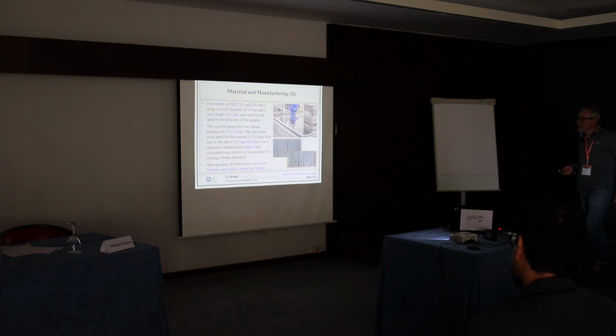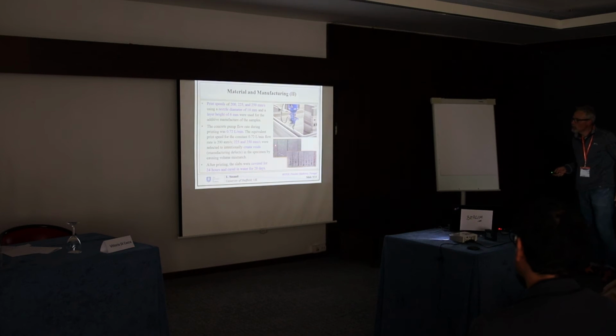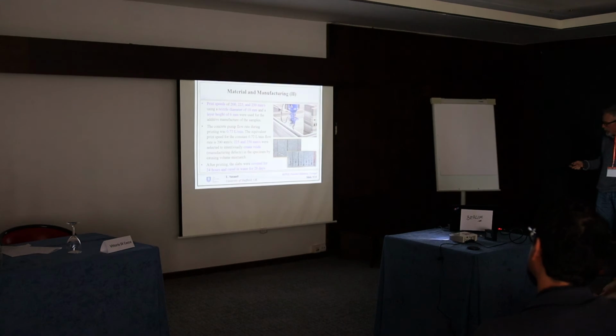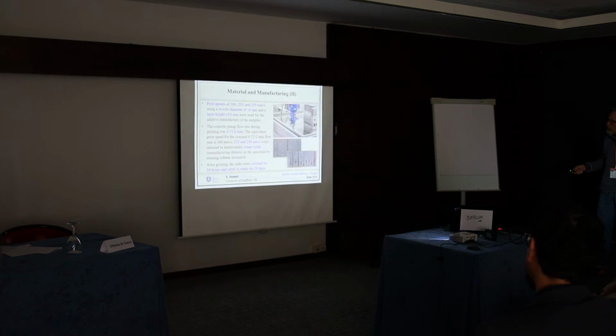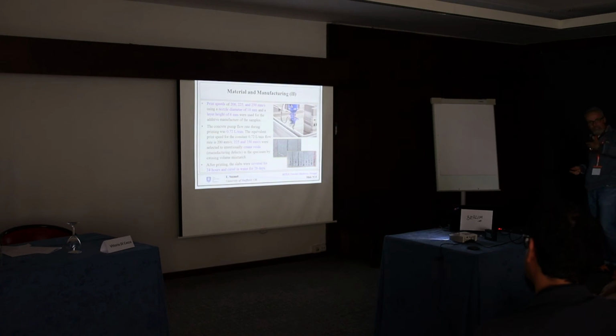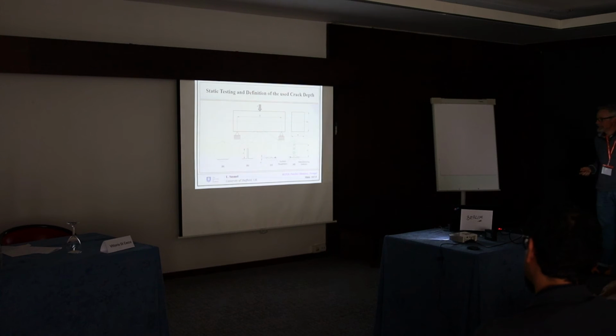So why did we change these parameters, the printing speed basically? Because if you control the process, you can get a very nice uniform material, as here. It's like a cast concrete. But if you start messing around with your 3D printing technology, you can end up having all these manufacturing defects. Okay? So we intentionally created a lot of defects, different levels of defects, so that we could explore the accuracy of our theory. Plus, there is another issue, and we will see the issue in a second.